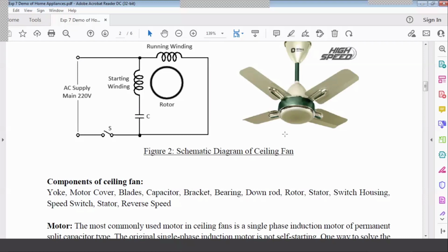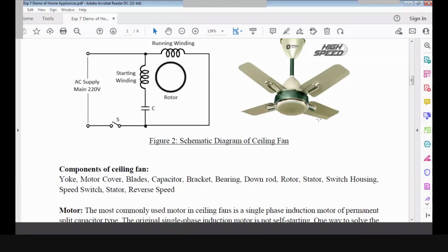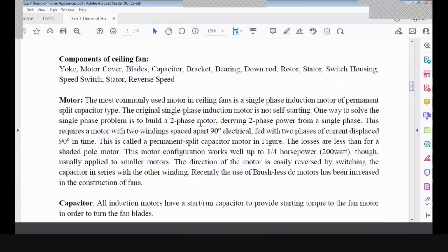Single phase motor is like this because we are giving single phase supply, so the flux generation is single phase and alternating in nature, so it cancels its effects. So the net torque is zero at starting, right? That's why if you want to run it without a capacitor, you need to use a two-phase or three-phase motor. If you convert this motor to two-phase, then it can develop the starting torque and run without any capacitor. But a single-phase induction motor cannot start.